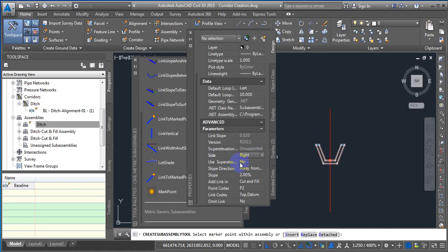This is really important when you need to work with roadworks. Slope direction, away from crown. Yes, this is important. And then slope. If I make changes to it, it's not going to allow me. For some reason, I think I need to restart my Civil 3D because I'm not able to make changes to this dialog box. But no problem, I'm going to go with the default, and then I can make changes somewhere else as well.